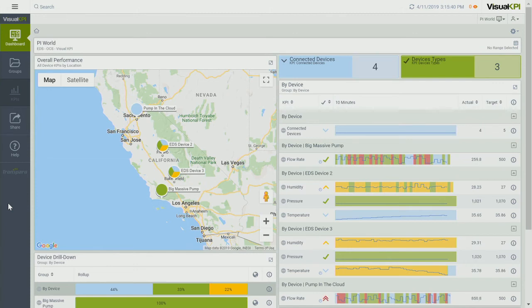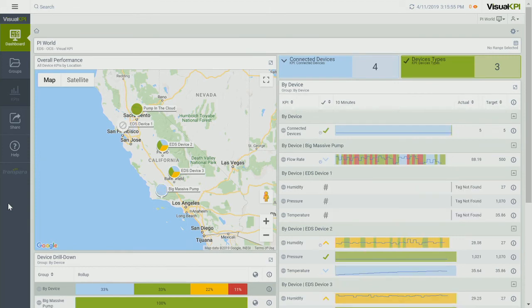The device has to identify, has to connect to the endpoint and say, you know, I'm alive. The endpoint has to say, well, what's your class ID so I can do something about that? We look it up in a database. Oh, you're a pump. You're a motor control center. You're whatever. You're a gas chromatograph. This is the things I need from you.